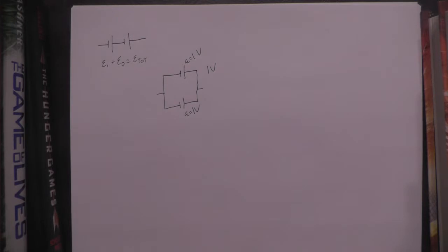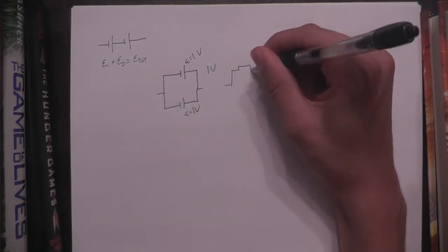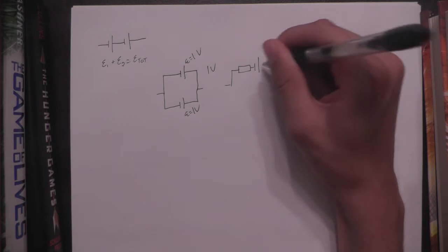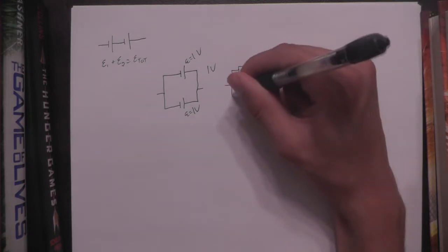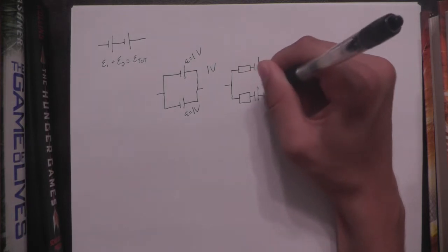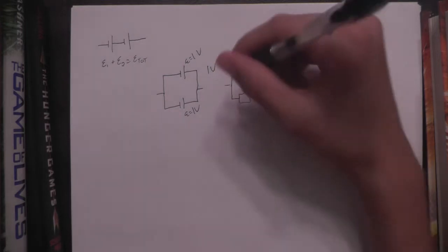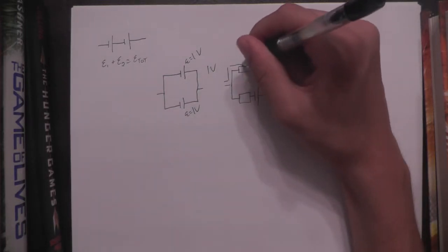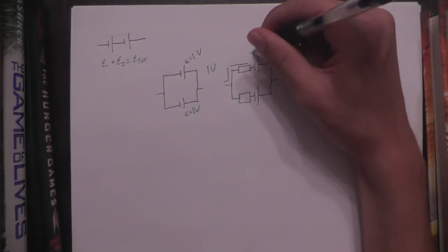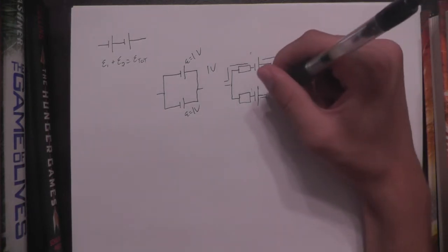However, if they're different voltages, there's no real way to actually determine what the total will be because you have to account for the internal resistances of each of the cells. Having different EMFs just doesn't make sense without internal resistance. You have the current going up, and it gets a lot of chemical energy converted to electrical energy here, but then not so much here.